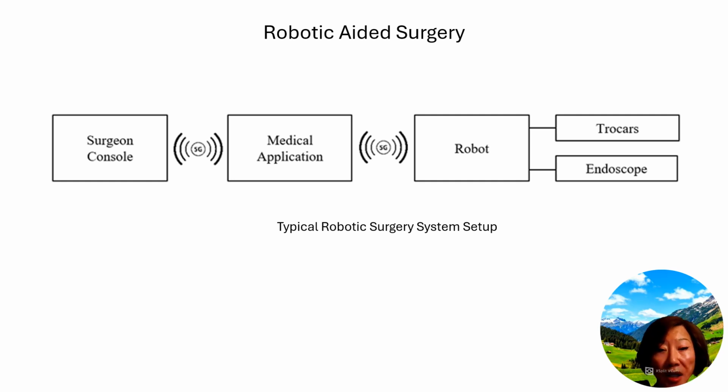This medical application can be instantiated either on site or in the cloud, with the role of generating appropriate haptic feedback based on instrument location, velocity, effort measurements, and images from surgical instruments, and a 3D preoperative patient body model. This provides tactile guidance by constraining where instruments, such as a scalpel, can go.